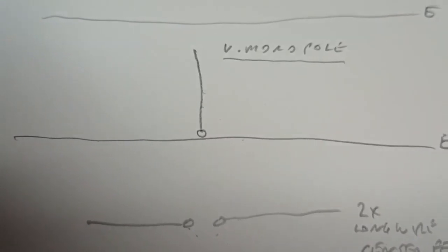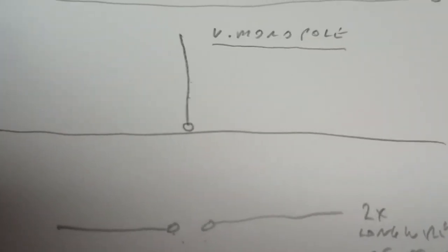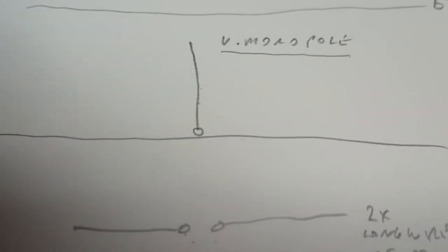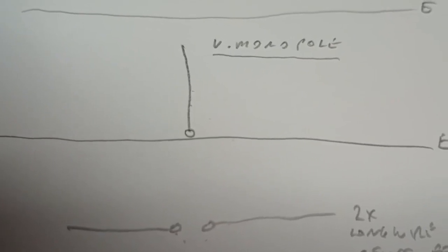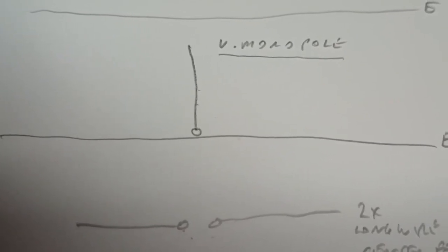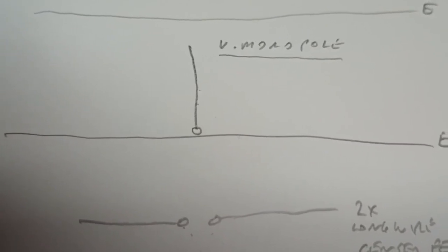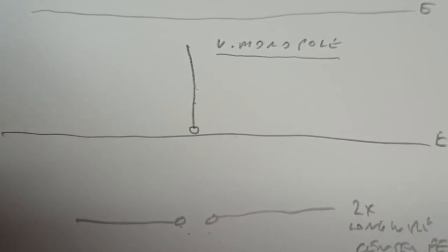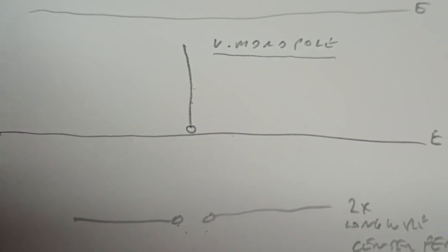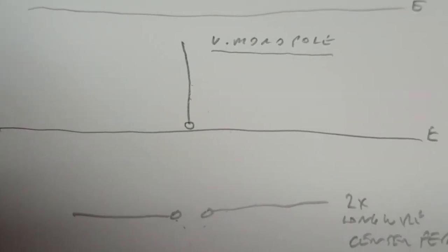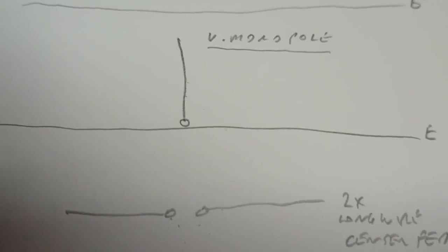The energy hasn't gotten to the antenna yet. Without the ground connection, there's no coupling out of the transmission line, so it's open. So therefore, the ground connection is not part of the antenna, and there is no such thing as an antenna with ground radials. The ground radials are for the transmission line, not the antenna, period.